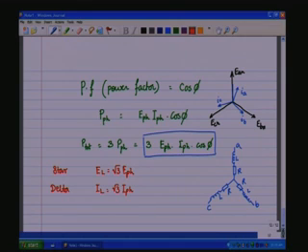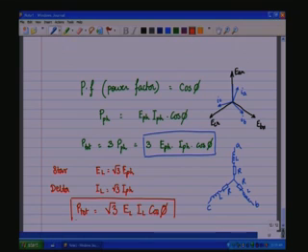If we substitute here, in both the cases you will see that P total will be root 3 E line I line cos of phi. So, this will be the total active power that is drawn from the load in the case of a 3-phase circuit.